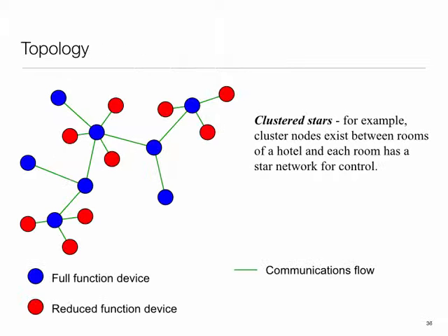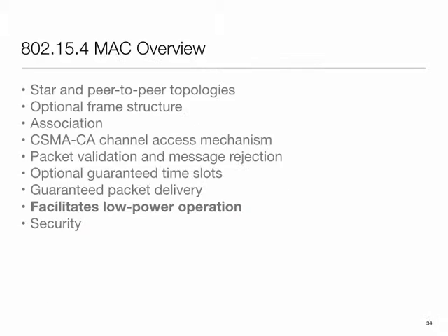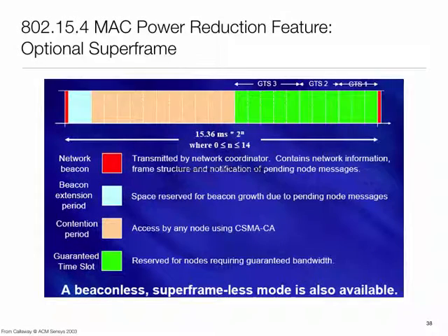So what's happening is, let me see if I have a good picture. Yeah. So what is happening here is the following: there is a large superframe consisting of what you can think of as tinier frames, and the whole schedule is advertised for the whole superframe. Then within each one of these intervals, since you know when to expect the packet for you, or when it is your turn to transmit or receive, nodes basically just wake up accordingly.